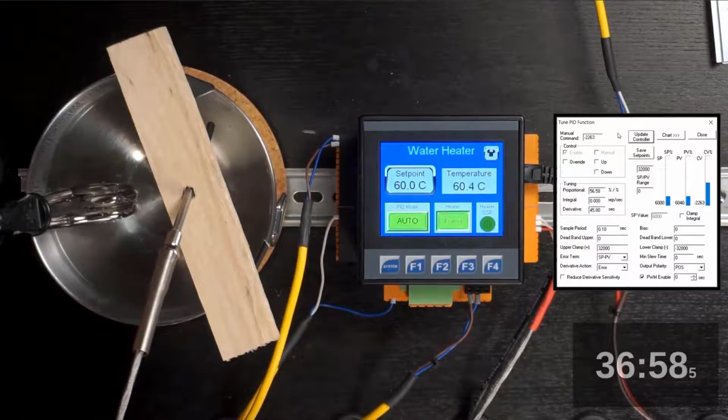Okay, now one thing I want to have a quick discussion of, and that is the proportional term. I haven't played around with the proportional term at all. If I go through and do a calculation on the different proportional terms I might be interested in using, basically the calculation I came up with was, say, 64 was about the largest proportional term I wanted to use. And that would be because of how close to the set point, for instance, when we're heating water that's just been poured in, how close to the set point do I want to be before I turn the heater from 100% off to some lower level?